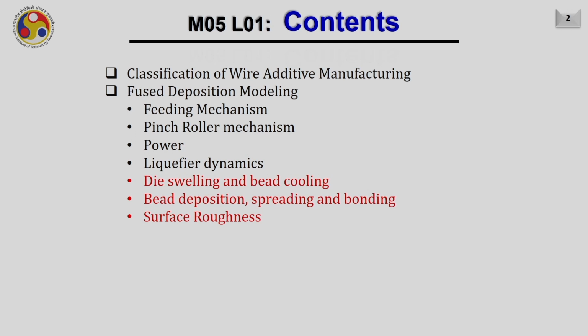Welcome to the fifth module. In this module, now we shall discuss wire additive manufacturing. So, in the first lecture today, we shall give the classification of the wire additive manufacturing processes. Then we shall discuss the most popular additive manufacturing process, which is also called fused deposition modeling.